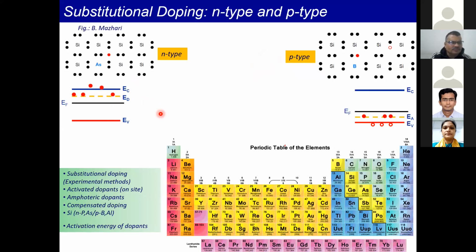Then how is it different from multi-layer films when metal is coated on the semiconductor film? Does it work the same way or a different way, sir? No, that is different. Here you are putting atoms in the material, so you are changing the band structure of the material. While in what you are mentioning, when you put metal on the semiconductor, we are making a heterojunction. That is where we were discussing band diagrams, where on one side we have metal and on the other side semiconductor. Right now, we are putting metal atoms inside the semiconductor, so we are changing the band structure of the material itself. Thank you.